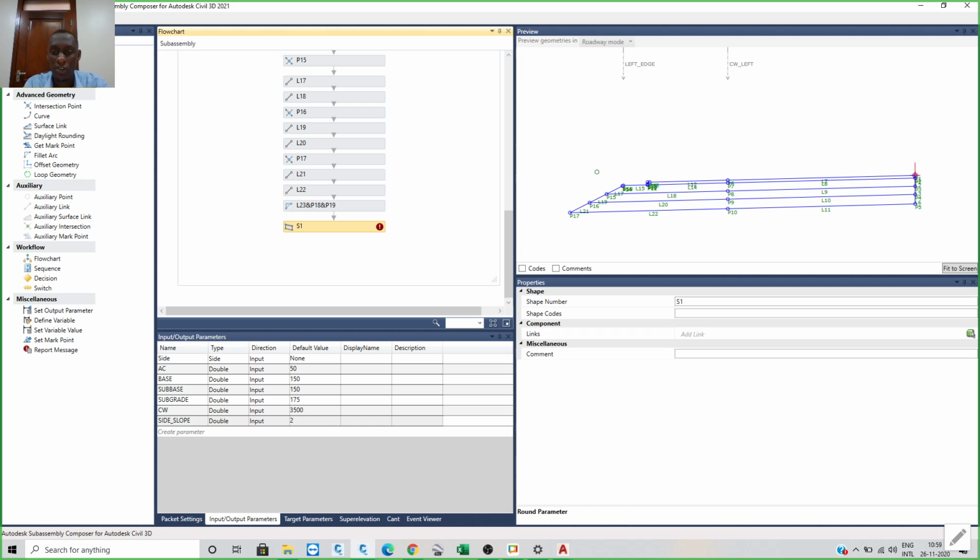So if you wanted to determine the volumes using this cross section, you will not have any volumes, because this is just a skeleton. It is only hollow and it has void. So we need to make it have a body. That is the purpose of the shape, because it is this shape that forms the body that calculates the quantities.